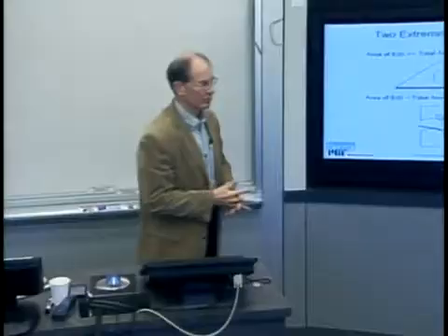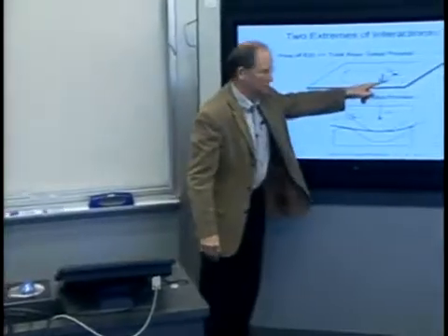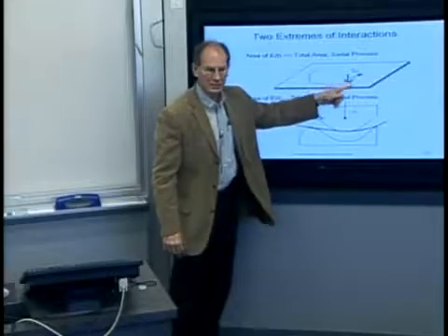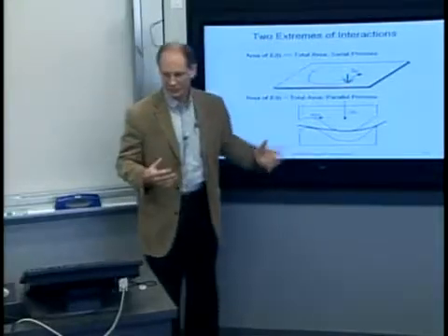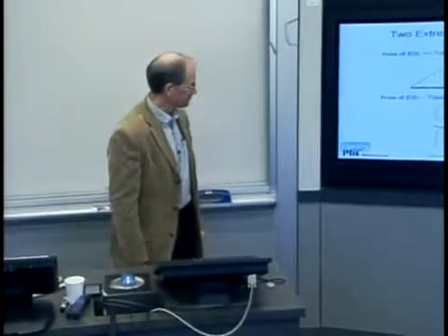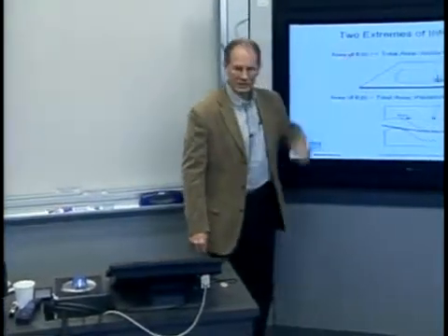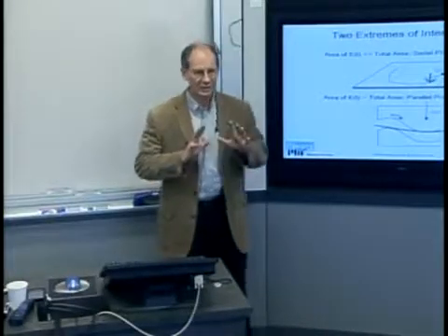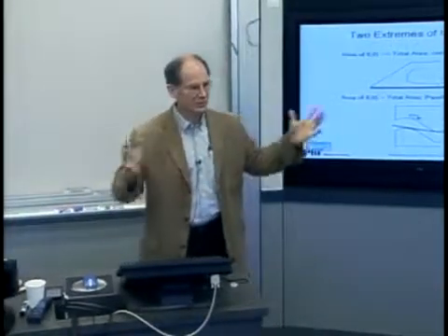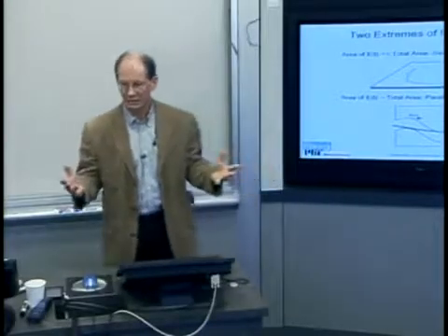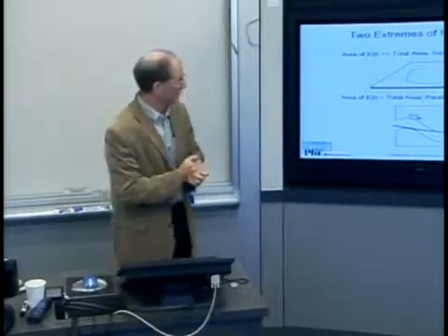Now, of course, in a real process, even with the femtosecond laser, if you get small enough, there are spatially distributed effects. And as I go to larger and larger tools, this gets worse and worse. But if we make a definition that the area of the energy interaction is small compared to the total area that I want to change, then it's clearly what we'll call a serial process.